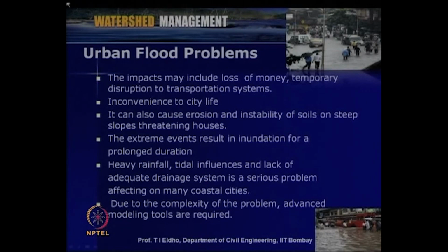Due to the complexity of this problem, whenever we deal with urban flood prediction, we need sophisticated tools like geographic information systems, with data from remote sensing, and very complicated numerical methods like the finite element method or finite difference techniques to assess the flooding possibilities.